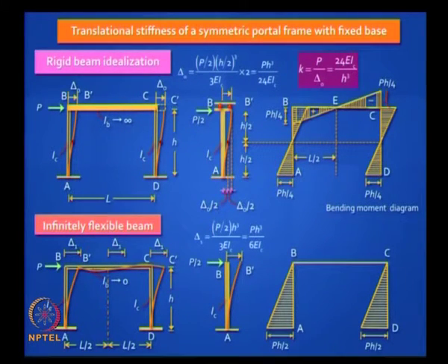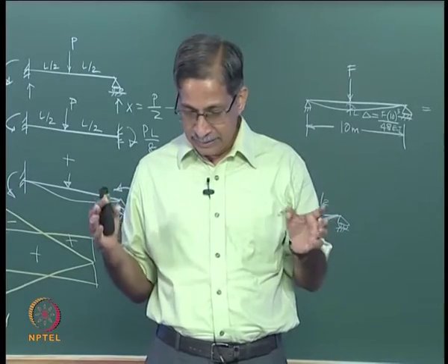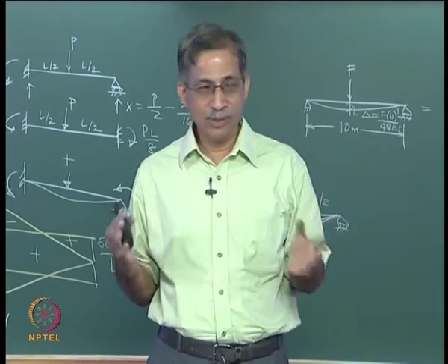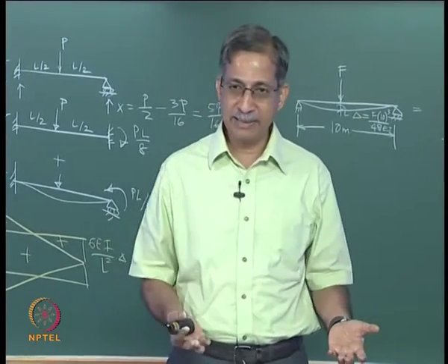that because your beam will have no bending moments, because you got hinges there. So it is very interesting. I have looked at all the extreme cases. The summary of this, so here it turns out to be 6 EIC by H cubed. So take a portal frame, a symmetric portal frame, take the base as hinged, your horizontal stiffness is going to vary between 0 and 6 EIC by H cubed. That is what we saw in the previous slide.